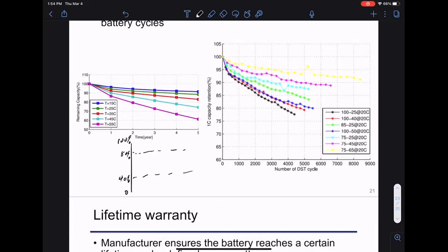All these complicating factors make the battery not as simple to use as we would like. If you naively pretend the battery is a black box and just use it that way, then what you quickly figure out is that after a year you don't have a battery anymore, maybe because you did not get the state of charge correct or charged and discharged too aggressively.